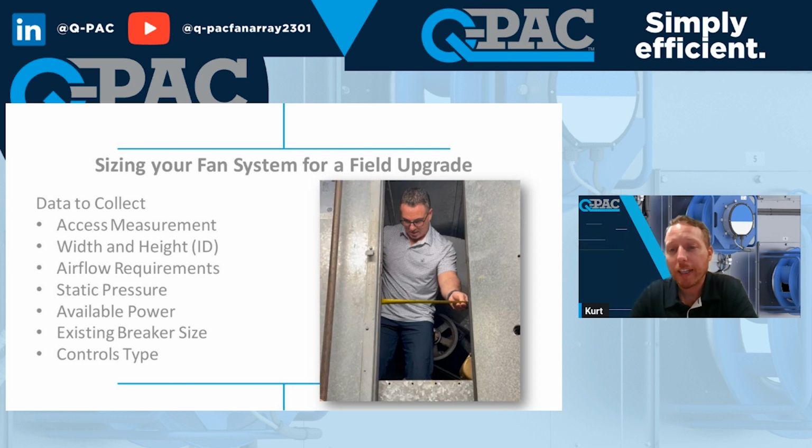And then the last thing is control type. So what does the customer want? Do they want to connect to BACnet? If they don't, they just want to feed it 0 to 10, you can use our basic option. So just understand what your customer wants and you can select the correct control type.